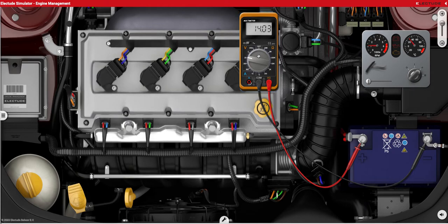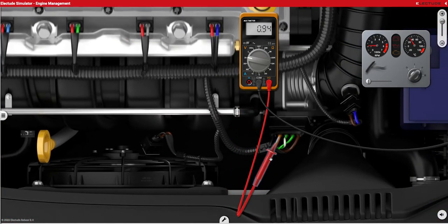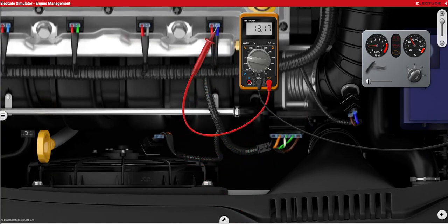You can also back probe certain connections and get voltage readings simply by back probing on the component. Here again, you might have to zoom in rather tightly to be able to place the pinpoint probe. The tighter you zoom in, the easier it's going to be to place the probe.